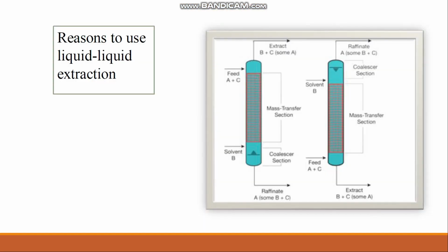The reasons can be summarized as follows: the separation not being feasible by distillation, the breaking of azeotropes, the energy requirements of distillation being prohibitive, the requirement of a complex distillation sequence, or the materials being heat sensitive or non-volatile.